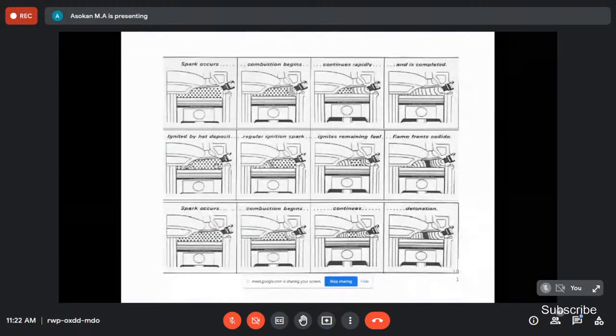Before sparking, see, this is the ignition, right? It starts because the temperature of the spot is already higher due to carbon deposited inside the combustion chamber. Due to this carbon deposit, it ignites the air-fuel mixture before sparking. Then automatically the flame travels in the opposite direction without the spark plug firing. Later the flame travels in the other direction, and sometimes both meet. So it is the pre-ignition.